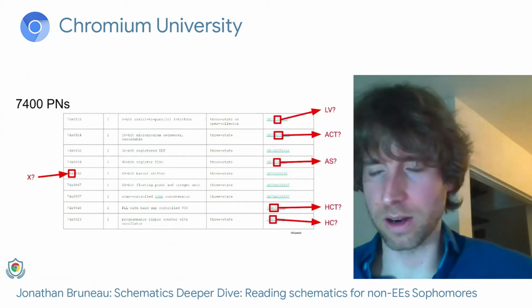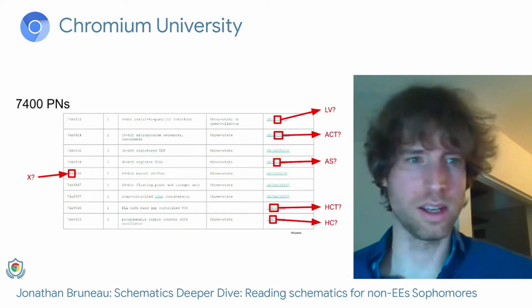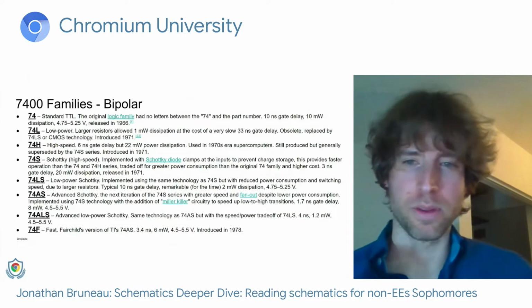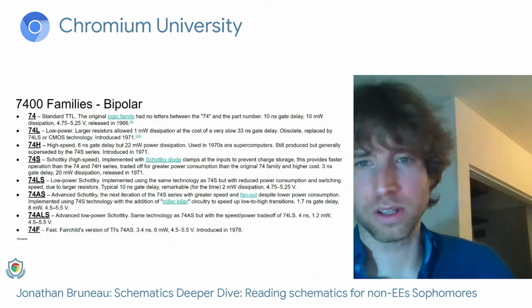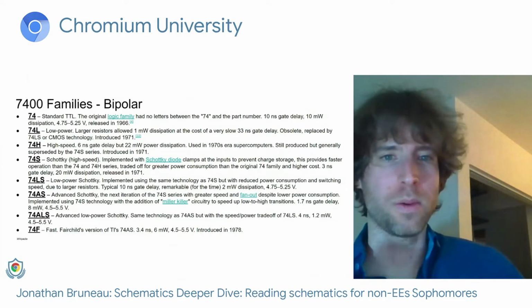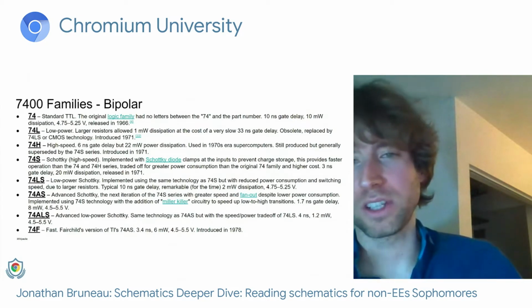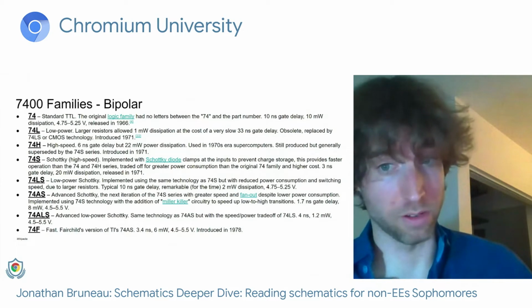But over here, I have a whole bunch of text between those two: LV, ACT, AS. What's going on? Well, remember I was talking about how the insides don't really matter to us. What matters is the pinout. Well, it sort of matters in that we can use different types of transistors to implement the logic functions, or the function of the chip.